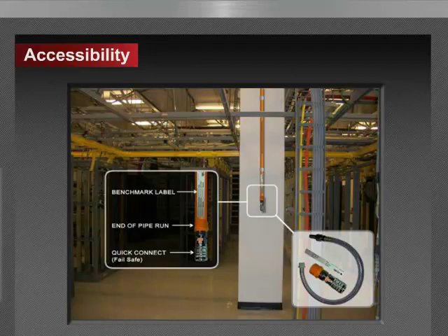With an air sampling detection system, it's very easy, and the process is essentially back flushing the pipe network, using, say, a vacuum at one end of the pipe, and generally disconnecting the pipe from the inlet of the detector when you're doing that process. So it's a very simple process, and you're cleaning the entire pipe network without having to physically get to each and every individual hole. I hope that answers that question. Great.